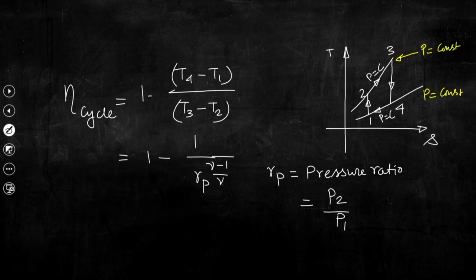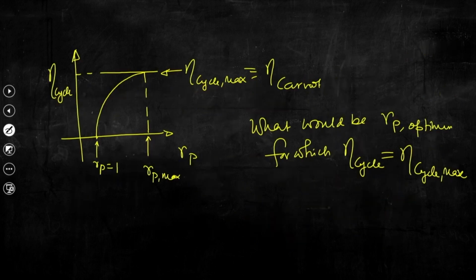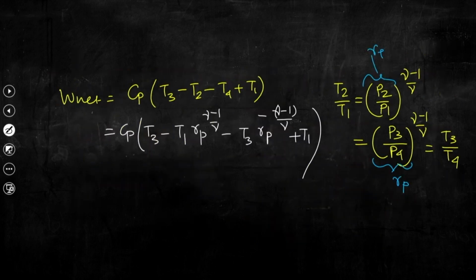that I will be discussing today, particularly for this cycle, the compression process is not only to raise the pressure of the working fluid, but also to increase the temperature as well. So, what we can do here, we can fix T3 and T1, and that is why we have replaced here T2 and T4 in terms of T1 and T3.